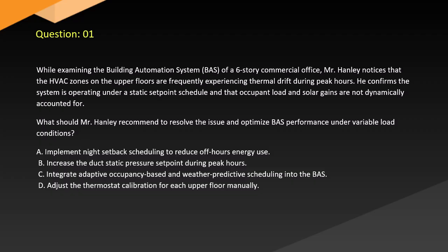A. Implement night setback scheduling to reduce off-hours energy use. B. Increase the duct static pressure setpoint during peak hours. C. Integrate adaptive occupancy-based and weather predictive scheduling into the BAS. D. Adjust the thermostat calibration for each upper floor manually.